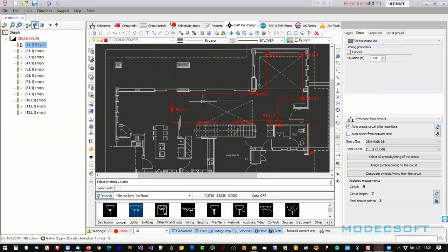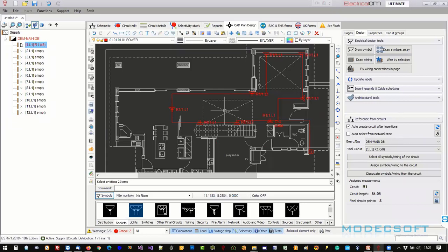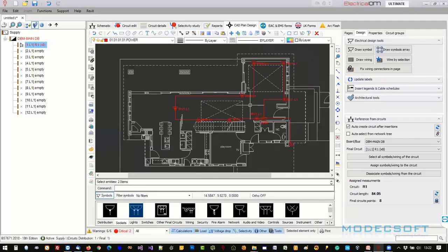And along the same lines, we've got a question about can we have options for cable tray in case the grouping of cables size. What we've done is we actually have within, and again, this will be something for the next one, we can use multi-lines. And we've got a number of predefined multi-lines, and you can also set up your own for different trunking sizes and run your wiring along those or within those multi-lines to show the path of trunking on that system. But again, that will be something for the next one.